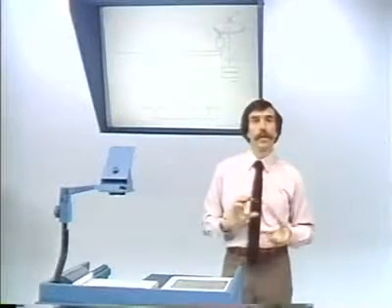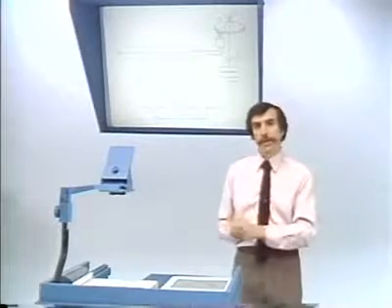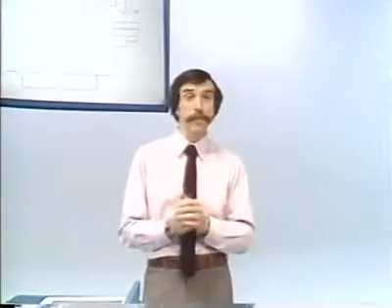Now, you could ask, why would you go to a digital or discrete time measurement rather than doing it the way I showed on the previous overlay, which seemed relatively straightforward? And the reason principally is that in the context of a digital implementation of the feedback process, often you can implement a better controlled and often also more sophisticated algorithm for the feedback dynamics, so that you can take account perhaps not only of the angle itself, but also of the rate of change of angle, and in fact the rate of change of the rate of change of angle.